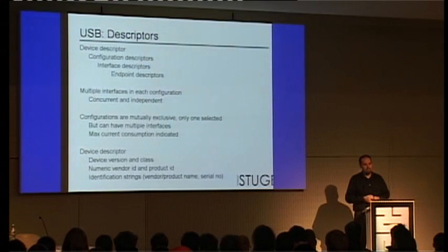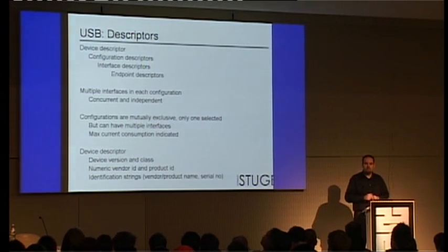either configurations or interfaces. They're using their own vendor-specific thing to switch personality of the device completely. So even though they could use these two configurations, they decided to make their device appear as only one thing at a time ever. When you first connect it, it's a CD, and if you send it some magic thing, then it's going to disappear. It's going to disconnect from USB and then switch something internally, and when it comes back, it's all of a sudden a modem. Does that answer your question? Yes. Thanks.